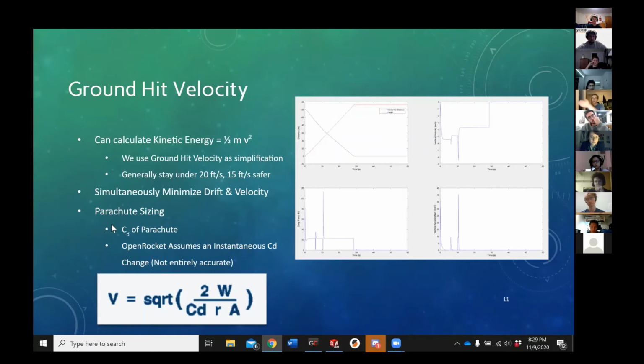If you take a plane and project the silhouette of the parachute onto the plane and look at that area. So say you buy a 48-inch parachute, then the radius is 24. So it'll be 24 squared times pi. That'll be the area. If you want to calculate your descent velocity, that's v down here in this equation.